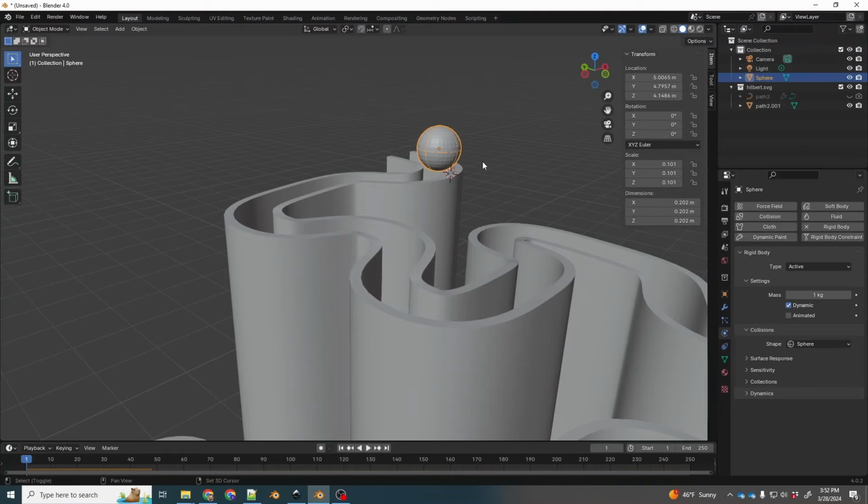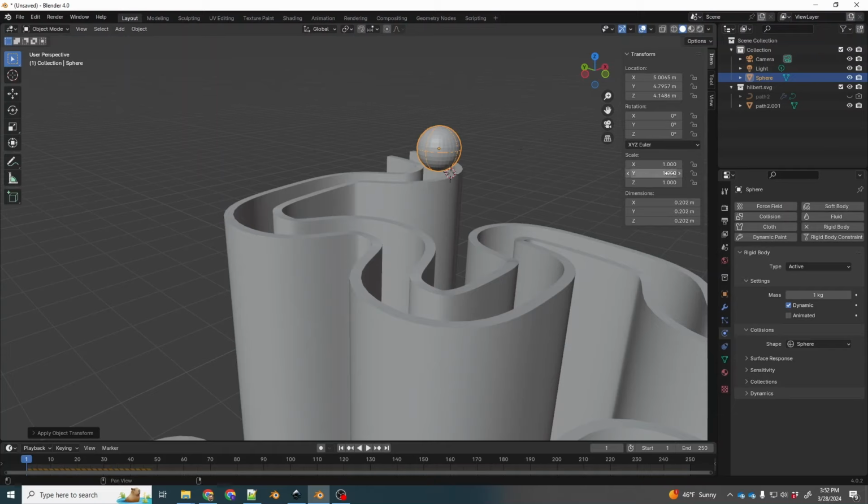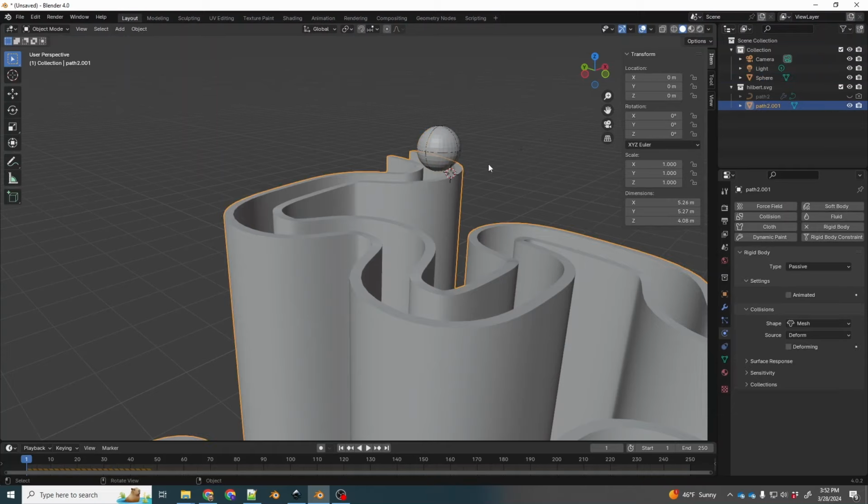okay, so now we haven't really applied the scales properly. So once you do any kind of transform, make sure you apply the scale. So scale, this should be 1. Make sure the other one is the same. Okay, so press space now and everything is in place.